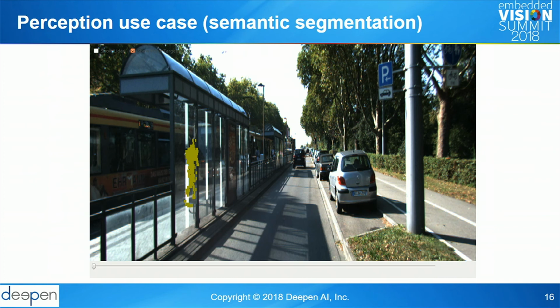Like I mentioned, LiDAR is great, but sometimes you really need camera. In this case, you're getting a bunch of reflections from that pedestrian over there. But on this street specifically, you don't really care that much about the pedestrian cutting the street. There's a barrier preventing them from doing so. That's where the high-definition map can make your decision-making prediction much, much simpler. If I know that on this street pedestrians are not allowed to cross, then I don't have to predict where that person is moving. A lot of it is science, but sometimes some simple hacks can help take you a long way. There's some more engineering that we can do.